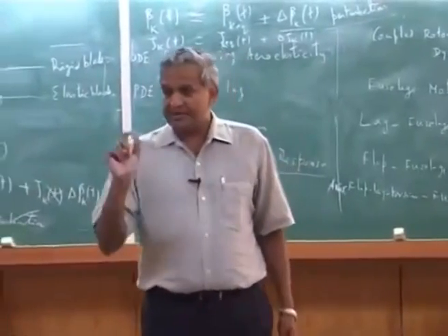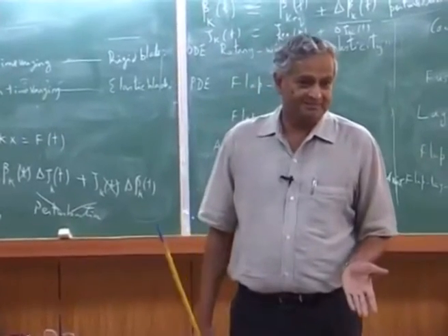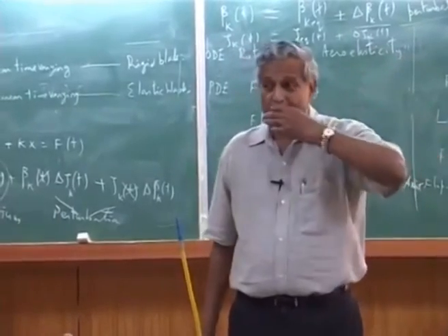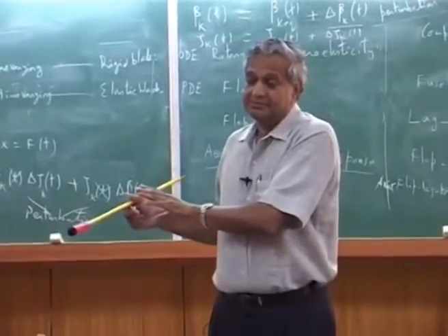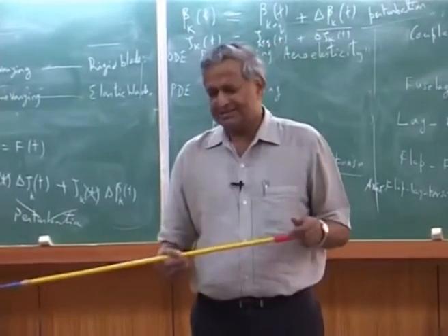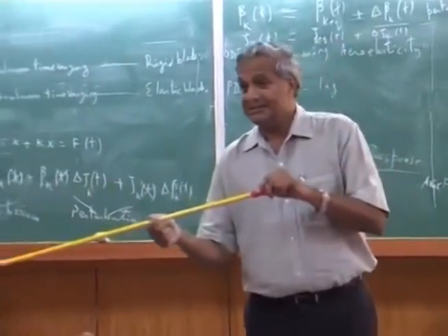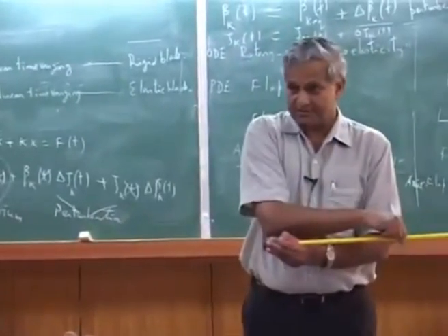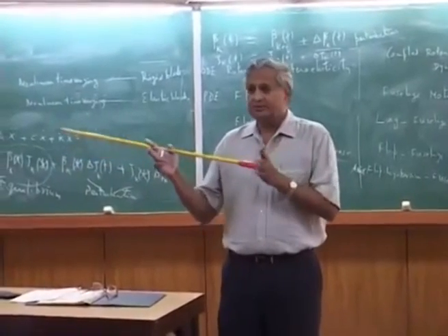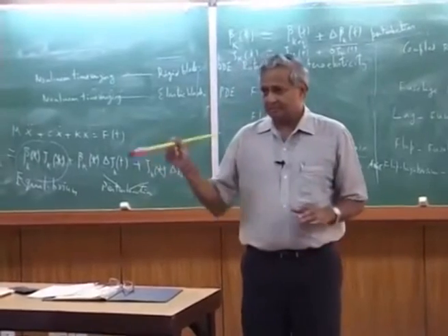But if it becomes time varying coefficients, how do you solve the stability? Well, there is one approximation where you convert this time varying system into another frame. That is called the multi-blade coordinate. But that is not an exact transformation, it is approximate. Convert the time varying coefficients to constant coefficients. Then you analyze. Another one is you apply Floquet-Lyapunov theory. That part I will teach in the last week.